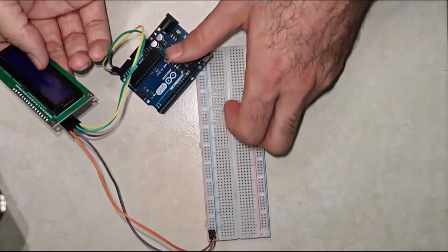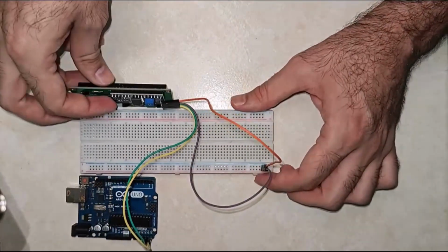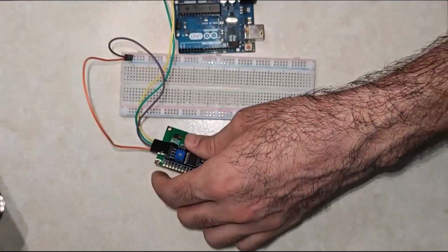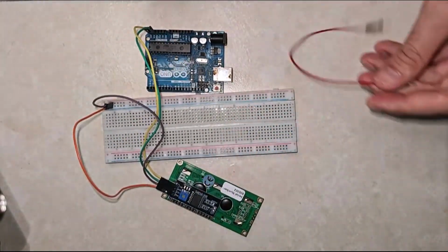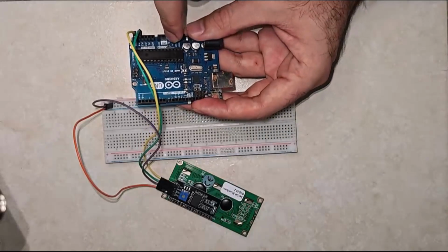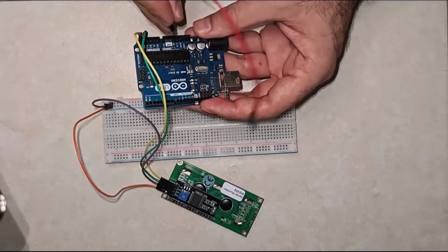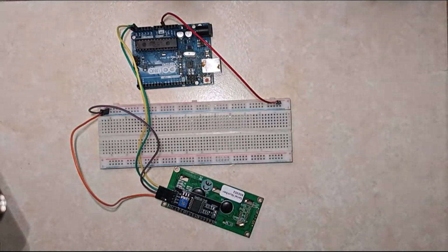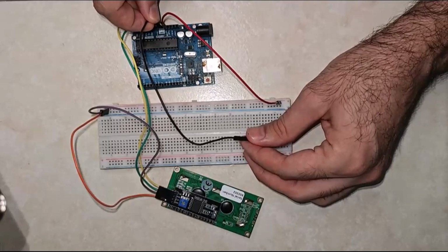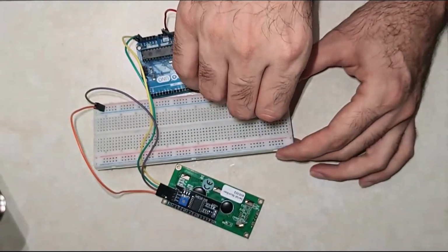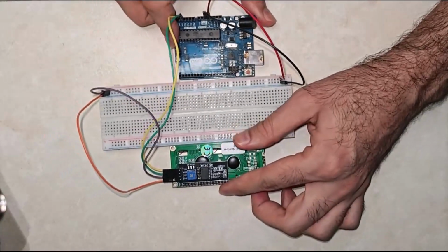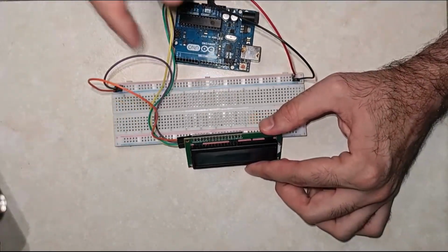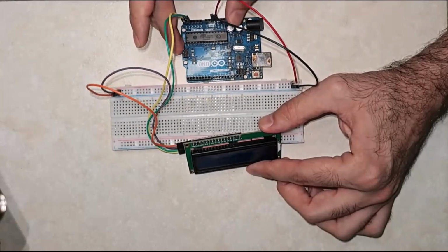This is for the wiring of today's project. Just one more thing, guys, and don't forget, we only have to connect this. See, let me just turn it so you can see better. So the 5 volts and the GND of your Arduino board. I'm going to connect the 5 volts to the positive, and I will connect the GND, okay, to the negative part of my breadboard. So this is the whole wiring and the hardware setup for today's project. So we connected our I2C LCD and our Arduino board.